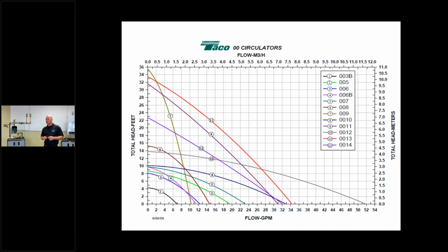Interesting question or a statement. Go ahead. This gentleman's got trouble with a low BTU load in a high performance home, small as well. Is there any way around a buffer tank? No, not really. I mean, even these circulators will turn down on pressure. You could look at the VT, but 4 feet of head is the lowest on the VT. So you'd have to really look at the circulator curves on a job like that. Even here, this runs at 10 feet of head. It will adjust its flow rate.